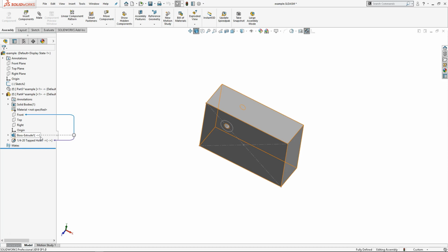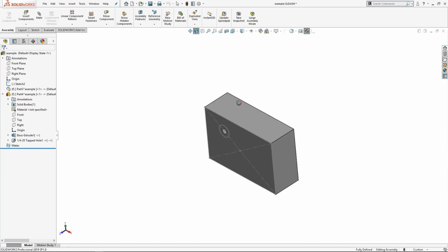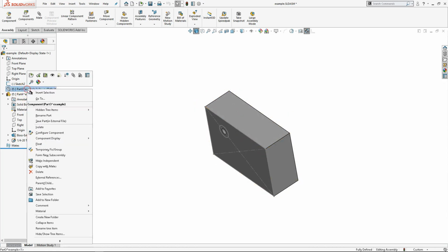This is where you can get into trouble, because as we name these, it's going to continue to look for the reference. It's going to look for this file name. We tie everything back to this one file name. Going into Windows Explorer and changing names is not a good idea. It will lose its mind, or you'll lose your mind trying to figure out what it did.